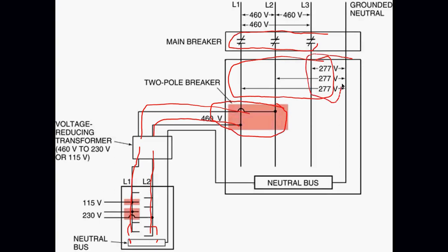What's my 277 volt used for mainly? Fluorescent lights and condenser fans. Yeah, less often condenser fans, but more often fluorescent lighting circuits. Be careful with lighting circuits. I've had plenty of building managers try to tell me that rather than call an electrician, I can just run the wire up to the lighting circuit to feed air conditioning units or refrigeration units. And it's not a good idea. It's not legal, and you might end up with more voltage than you really wanted.